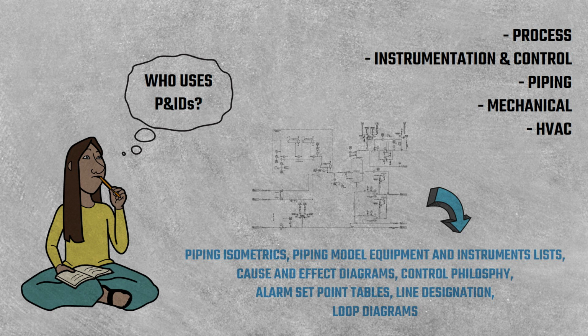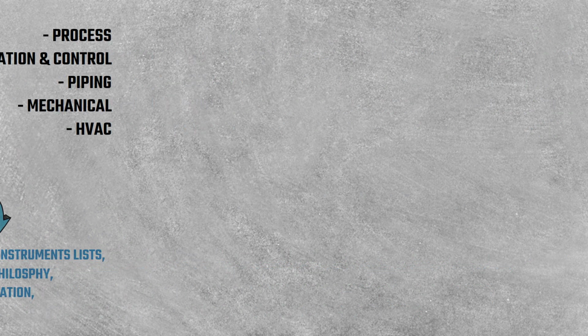So, all the groups involved in a process plant should be familiar with P&ID to some extent. It can be considered the source document to prepare a shopping list for piping, mechanical and instrumentation and control requirements. Instrumentation, controls and process groups should be fully knowledgeable about P&IDs because they are the main developers of P&ID, together with mechanical or electrical groups who can also provide some input during development, such as the equipment list from mechanical engineers and motor list and electrical classification list from electrical engineers.